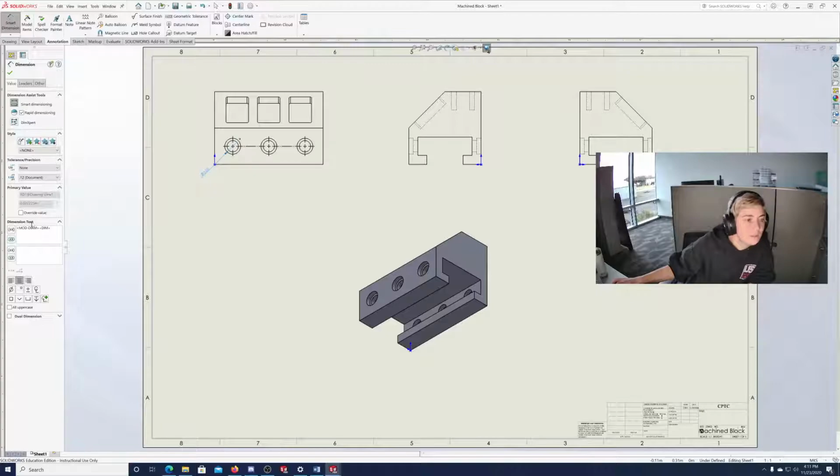So down here in dimension text, you can add that in. You can say like times 3. So now they see like, okay, it's 0.02 times 3. That times 3 there means it's referring to 3 different spots on the drawing. So it's referring to this one, and this one. And so you can edit your dimension text.